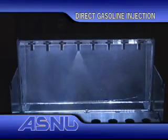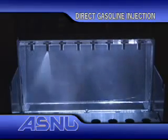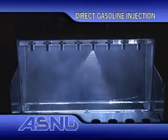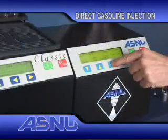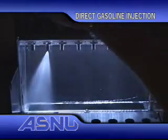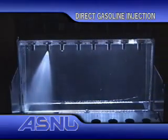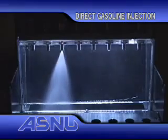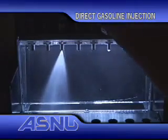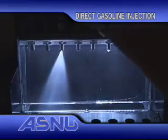For ease of use, in some operating modes the Asnu system opens the injectors for a much longer duration. The injectors can be operated at various RPM and millisecond settings, restricted only by the number of injectors being tested in the sequential testing operation. The Asnu also has a single injector selection feature, and with the ability to rotate the injectors for closer inspection of the spray pattern, the technician's diagnosis can be far more accurate and critical.